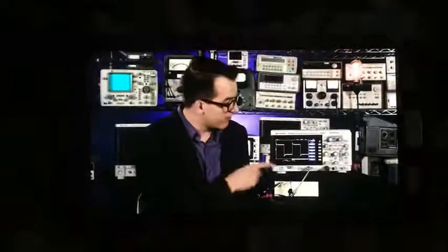So with our series inductor, you can see these spikes show up on the oscilloscope screen. And what's happening is when the signal is low, the inductor is charging up, and as soon as the signal switches high, it's pushing that energy back into the system, and that turns up as a spike on the screen.